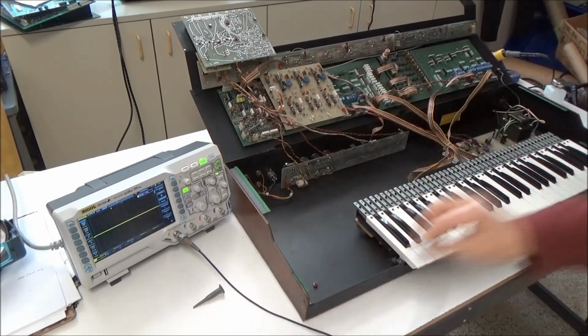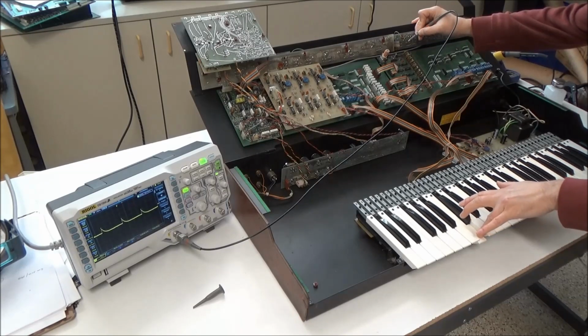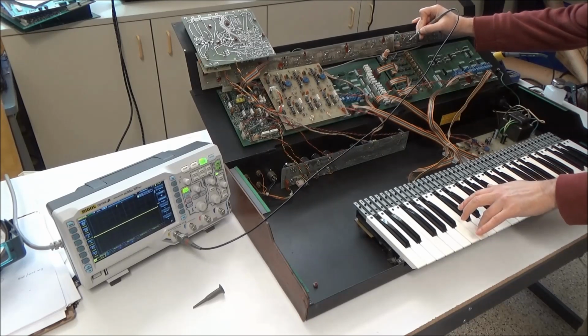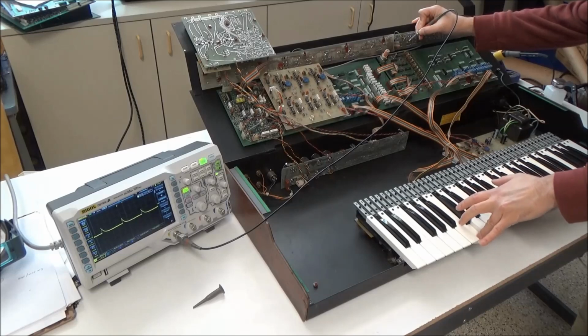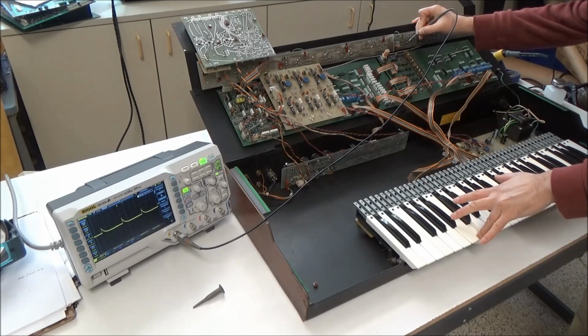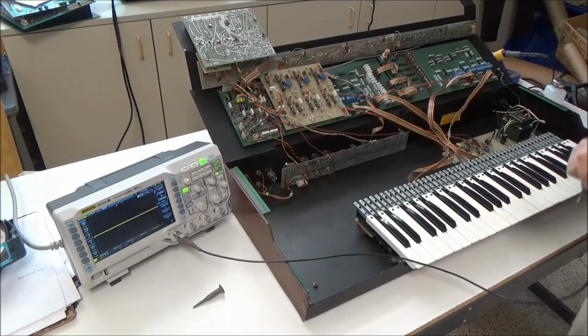So we're going to probe the analog switch. This is the wave coming into the analog switch, the 4016, and pin 2 is going out of it. And it looks the same. The oscilloscope's triggering fine. There's no noise, which would show up on the oscilloscope as random waveforms in the output. So it looks like the analog switch is okay. Now we'll get the block diagram and see where to look next.